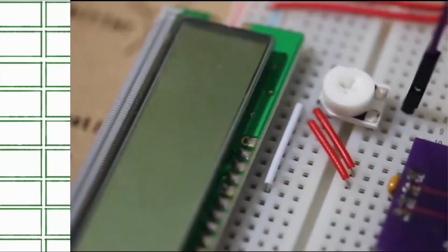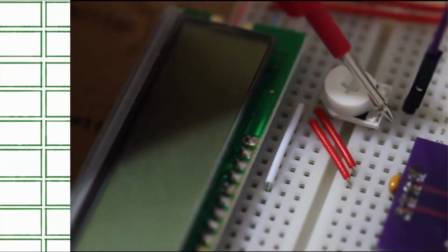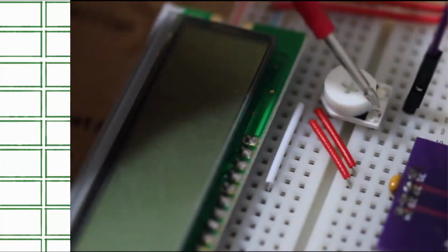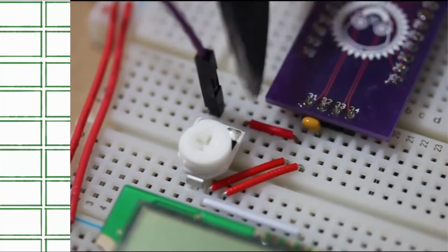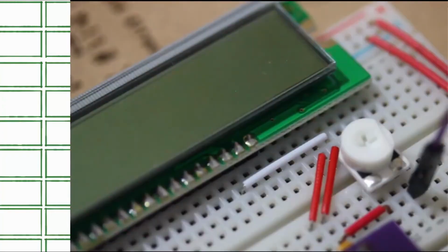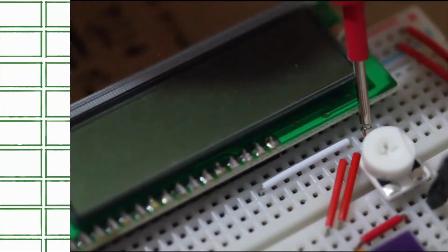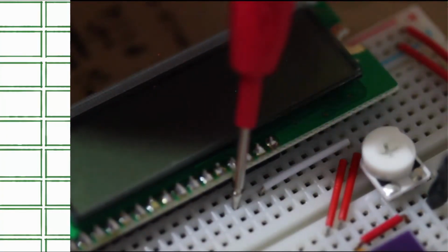So I'm just going to take a jumper and put it from this position, which is the 31 on the controller card, and that's the ground pin, and it's going to go to the ground pin of the LCD. So now I'm going to take the 31 ground and connect it to the potentiometer. So the potentiometer will have a ground and a 5 volts. So now we have the potentiometer connected to ground at the 31 pin. I'm going to go ahead and connect the wiper pin here from the potentiometer to the V0, which is all the way over here.